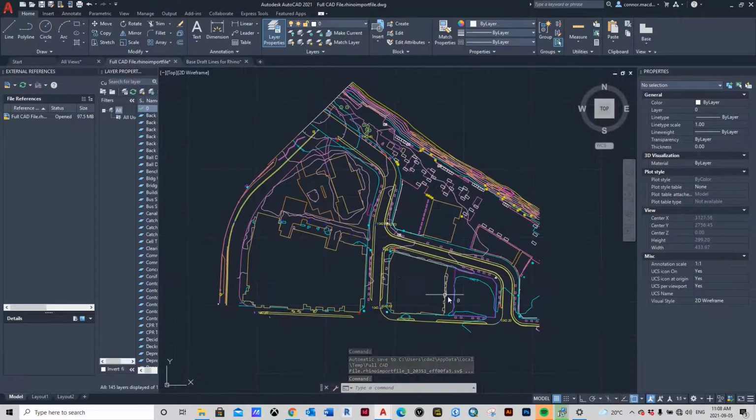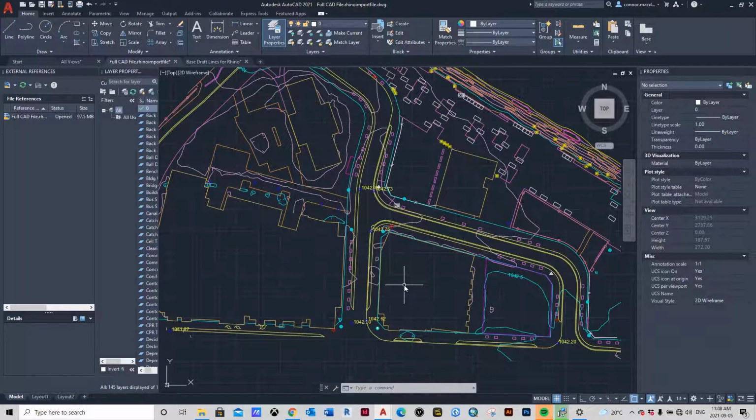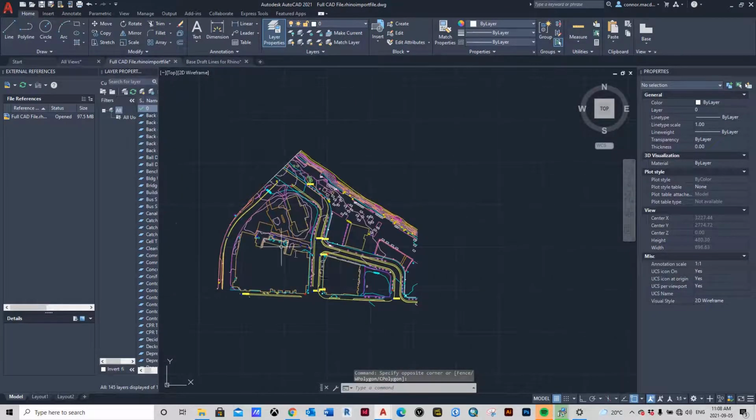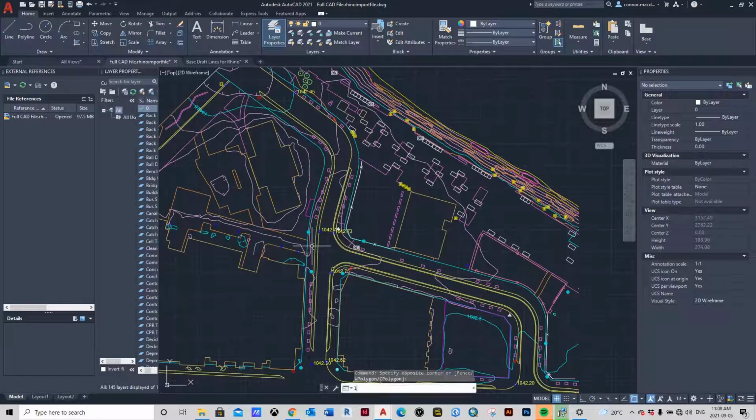The layer delete tool is very, very easy to use. Whenever you type anything, you can go down to the command line here to physically type if you want, or you can just have your cursor out in the open and start typing lay del. That's Laydel, lay, and that activates the layer delete. Then you hit enter, and it's going to ask you to select objects on layer to delete. Great, so that's what we want.